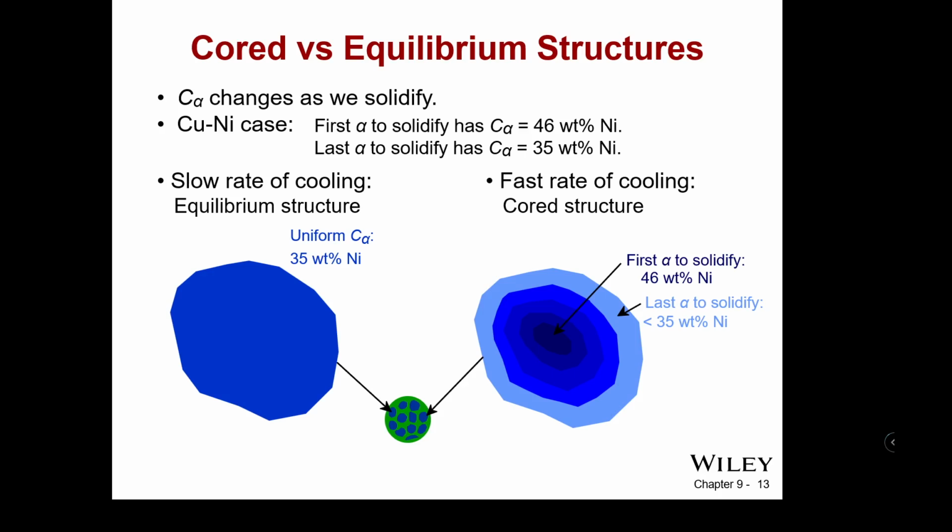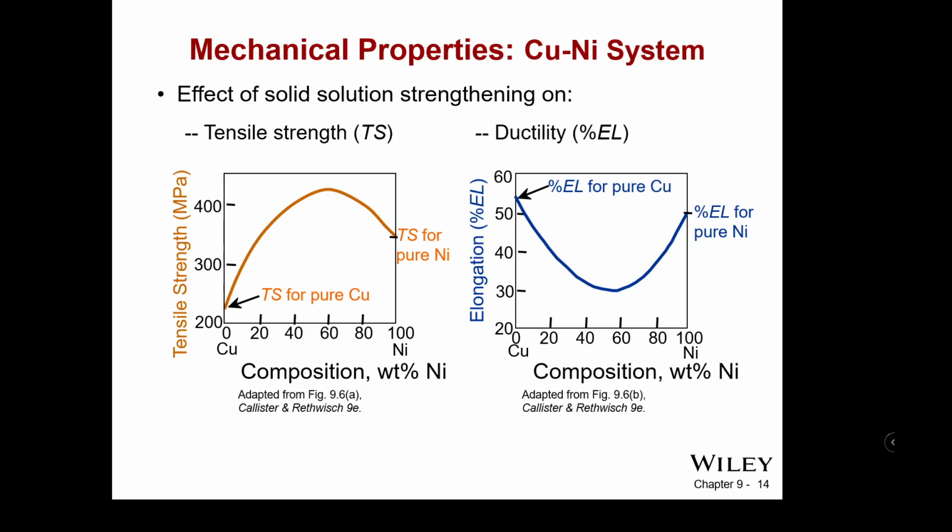The case on the left side here is slow cooling, like pulling it out of the furnace and letting it cool in air. This is rapid cooling, which creates layers of decreasing concentration. So it is possible to get higher and lower concentrations and have unusual tiered grains like that.